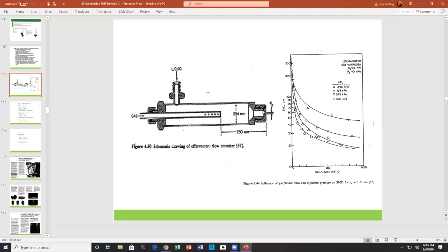You could possibly consider what's coming out of this as foam rather than a liquid stream. Okay. And the foam is going to undergo a volume expansion as the pressure drop is reduced. The liquid won't expand much, but the gas will expand a lot. And you would probably have expanding bubbles coming out of here. For data on such a thing, air to liquid ratio is important. Interesting is 0.1 and 0.2. Now, other data in the other lecture will take this up to 2 or 3.